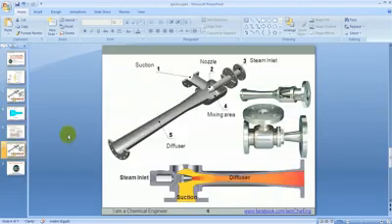So let's get back to the jet ejector. This nozzle right here is where steam is introduced to the system. As we can see, this nozzle is manufactured like this, so its area is getting tighter and tighter. At the final point here, it would be a very low area, so the velocity would go very high.